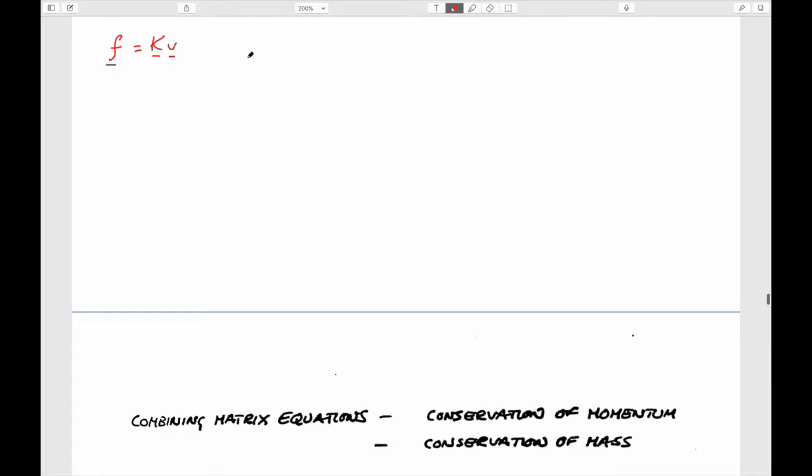I suppose you don't need a very sophisticated element to show this. If we wrote this out for a single element, we would write out the stiffness expression with F1 and F2. In other words, we can define at node 1 either a force or a displacement, and also at node 2 a force or a displacement. Then if we wrote out the stiffness expression, we know what it is: AK over L. You'll remember, right?